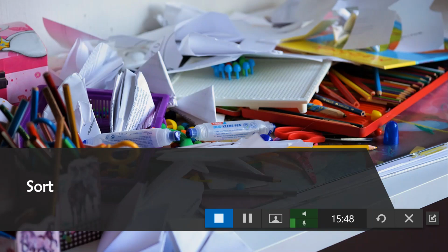The objective of sort is to identify items that are not needed in a work area to get rid of them. This is done through a process called red tagging. During a red tagging project, you can examine your work area to identify any environmental health and safety issues at the same time, using yellow tags or other visual cues to identify problems to human health or the environment. Yellow tags highlight the environmental health and safety hazards or improvement opportunities. The basic steps in yellow tagging are the same as in red tagging, so you can implement them together or separately.